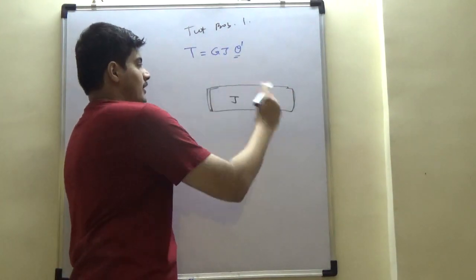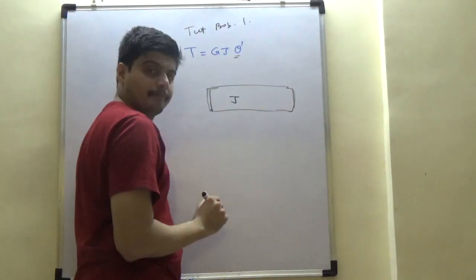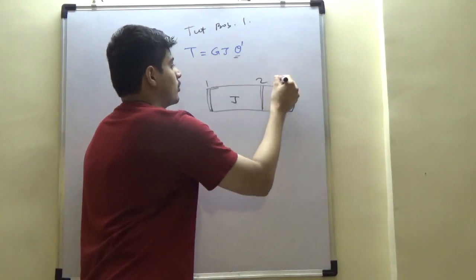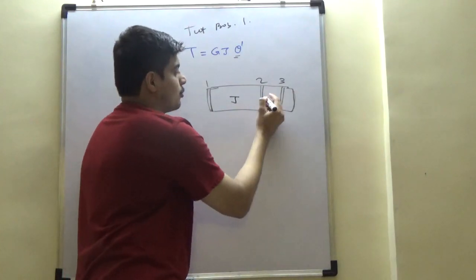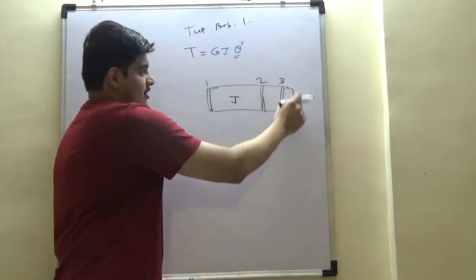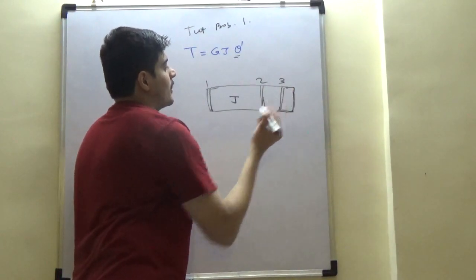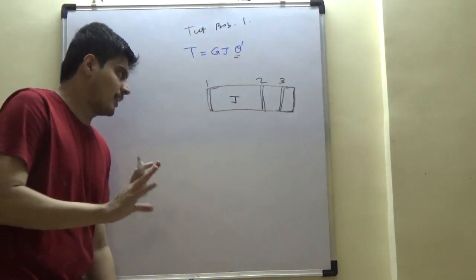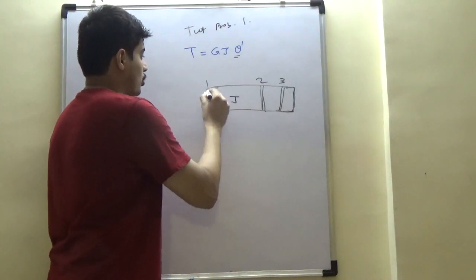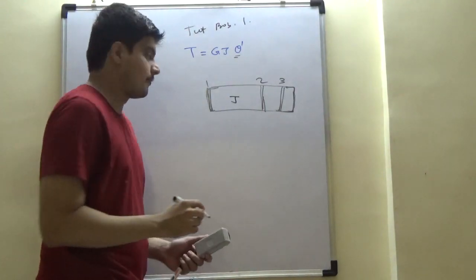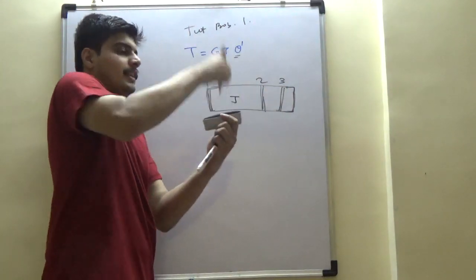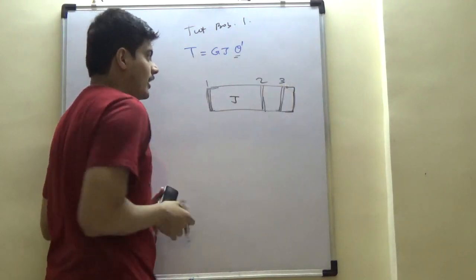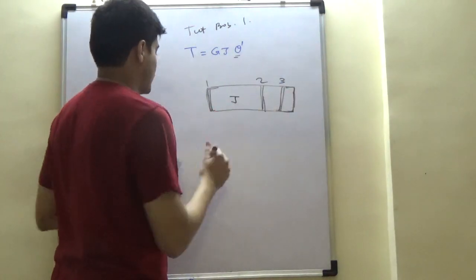There is going to be torque as we discussed, right? These are the different wing sections. I am going to call them 1, 2, 3 just for convenience. Some next to the middle, almost towards the end, right? Extreme edges we will ignore because, as we said by St. Venant's principle, some of these end effects of stress are local, so we will ignore. This is the root chord, which is attached to the fuselage. This is getting distributed with lift, right, and its twisting moment, which means the torque which is generated by aerodynamics, is going to twist this wing.